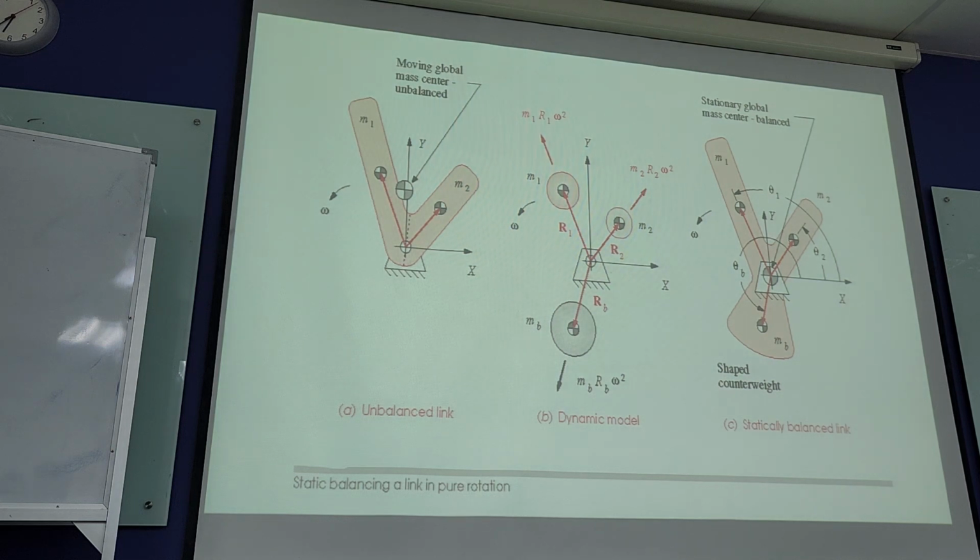So in the last session, we have done some questions by drawing some of the moments to 0. That means drawing the moment polygon, and then drawing the MR polygon. By drawing those two polygons, you can easily do the balancing equation. So the next question, you can do very easily for 20 marks, will be from balancing.